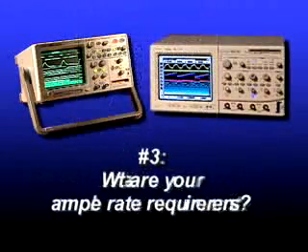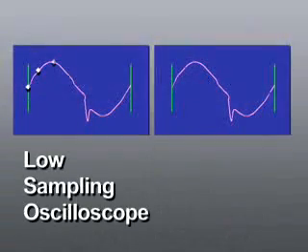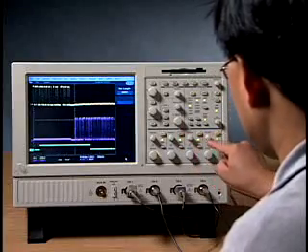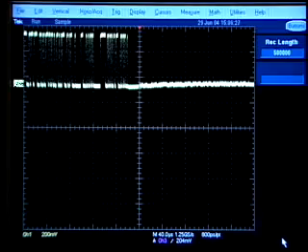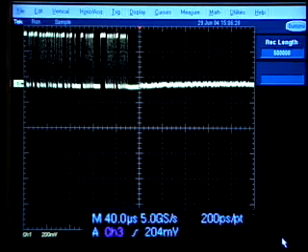As mentioned earlier, sample rate should be a key consideration when evaluating any oscilloscope. Sampling rate is the rate at which the scope can take a snapshot of the incoming signals. Higher sample rate translates into better real-time resolution. Most oscilloscopes incorporate a form of interleaving. This involves increasing sample rates when 2 or more channels couple their A to D converters to provide a maximized sample rate on only 1 or 2 channels of a 2- or 4-channel oscilloscope.